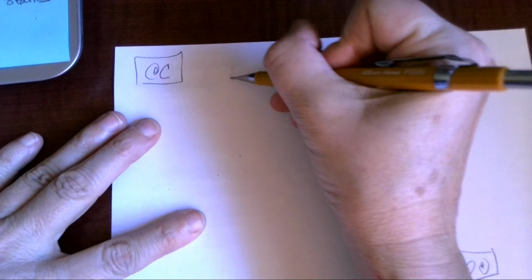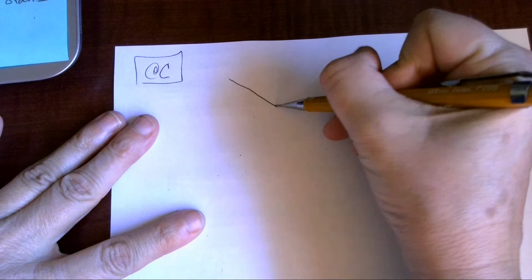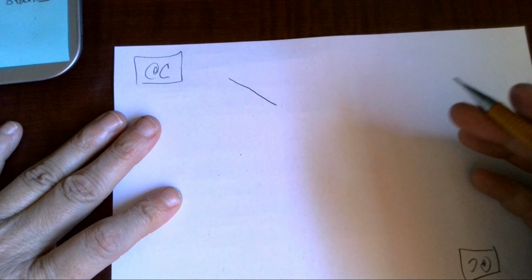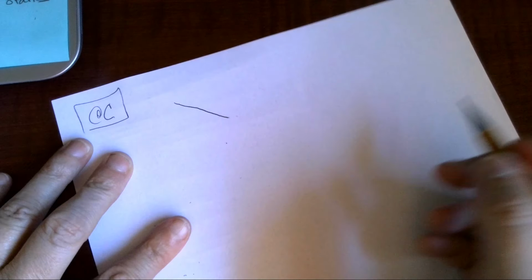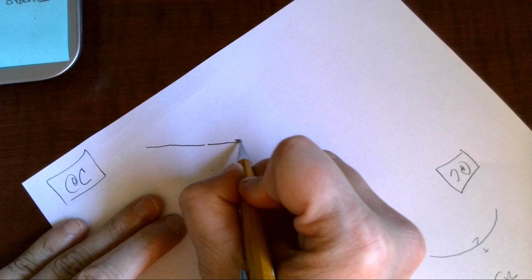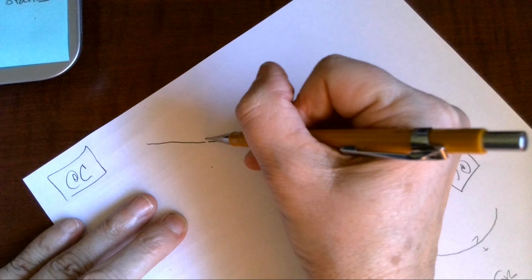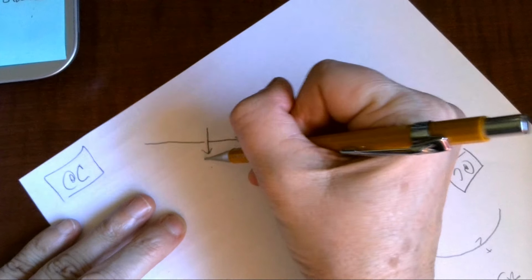So at C, when you look at that free body diagram, you can come from the left to the right or the right to the left, and I'm going to choose to go from the left to the right because it just has less mess and less distances. Again, when I draw my internal forces, normal is always perpendicular to my surface, shear is always parallel, and then the bending moment.